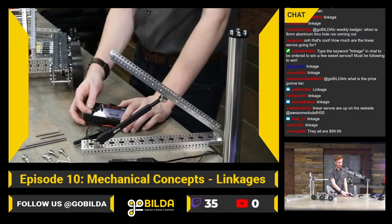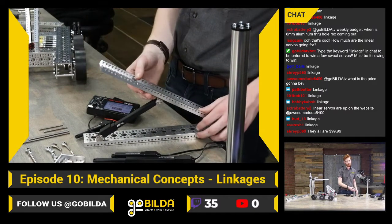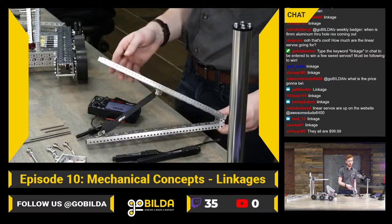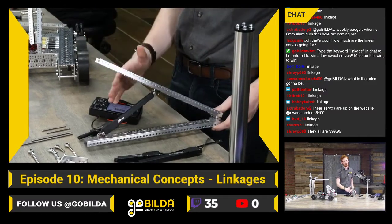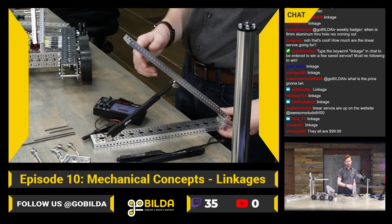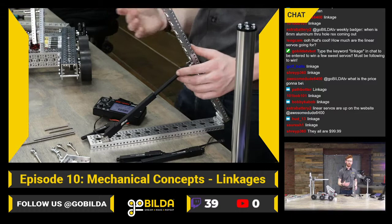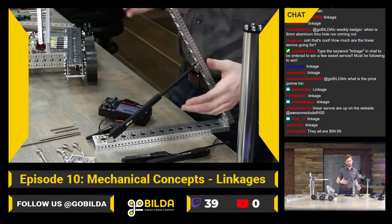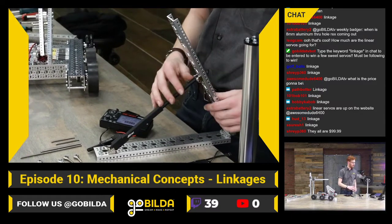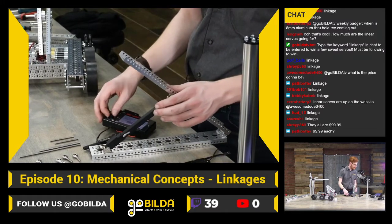They are really good at getting a lot of power behind a long lever arm like this. And really what we've created here is a 3-bar linkage with one of those bars able to expand. That can give you a lot of torque on this arm, and it can be a really nice effective gear reduction on the overall length. It looks like they are also all up online right now.